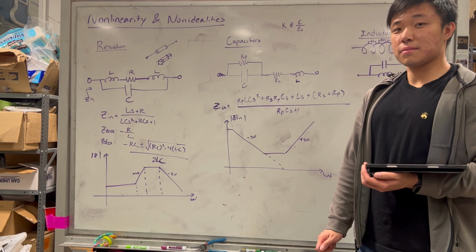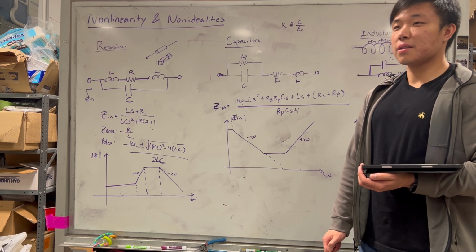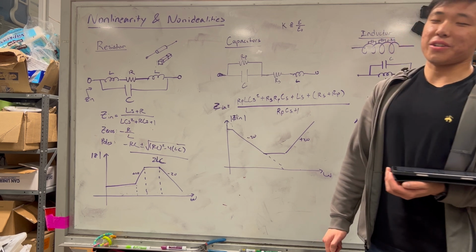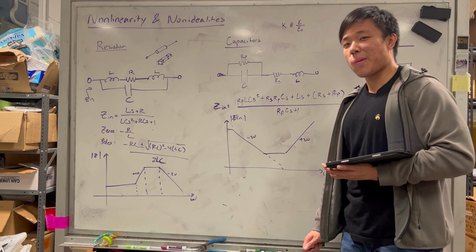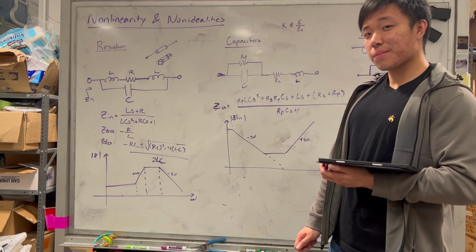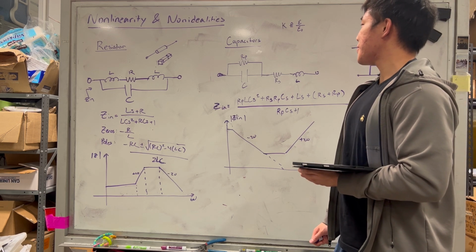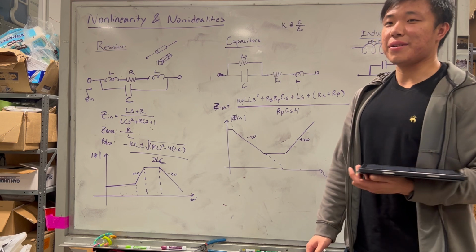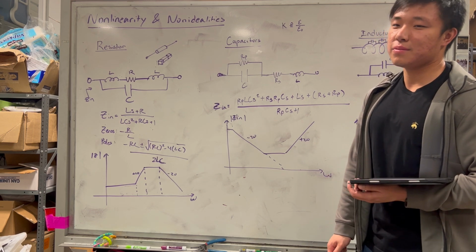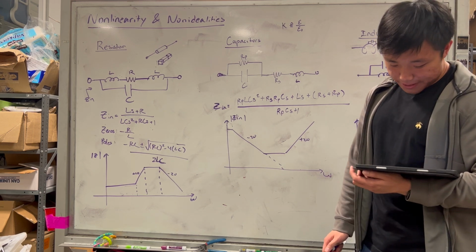As ambient temperature goes up, it messes with it more. Yeah, it changes quite a bit. So you don't want to use too big of a K because of that reason. It'll deviate a lot from what capacitance you expect.